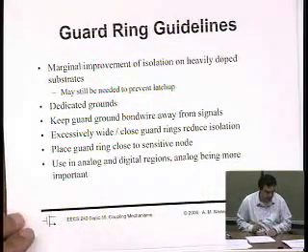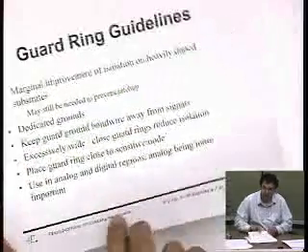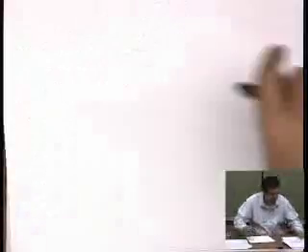Some guidelines on designing guard rings. I'm going to just stop there about substrate. Let me just ask you guys a question. Why do we use, actually I asked this question already, why do we use this highly conductive substrate? Well, it's to prevent latch-up, right?